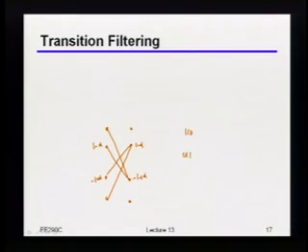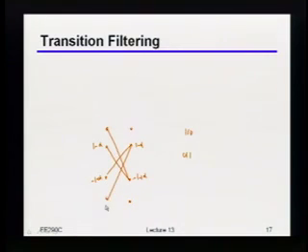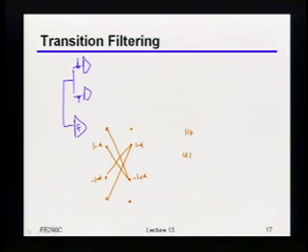We said there were a bunch of different ways you can deal with this, but one way, if you wanted to simplify the hardware, so that all you need is your 2 samplers for doing the loop unrolling and an edge sampler where you don't want to deal with adding in extra offsets, then one way of making that loop work, although you are sacrificing the update rate, would be to say you're only going to use this update when you actually detect this clock transition.